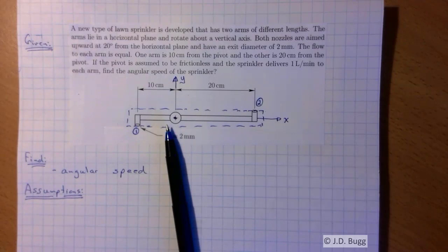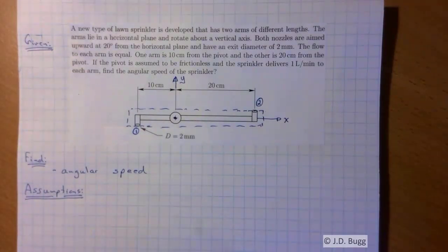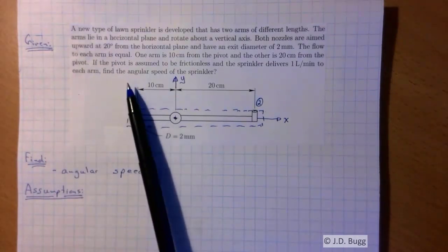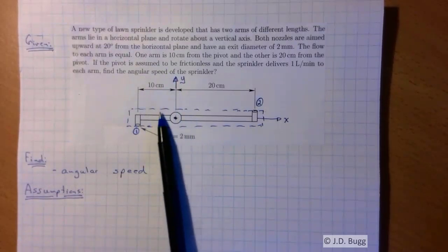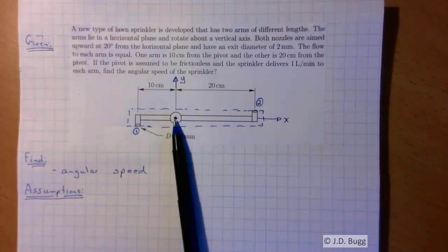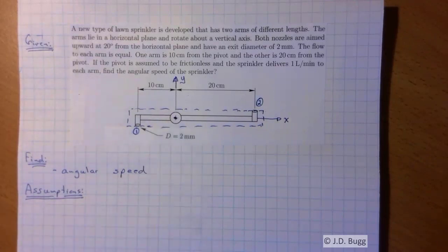So we can't quantify the torque due to the body forces, but we can say that whatever it is, it's going to be in the j-hat direction. Well, why is that important? Well, again, conservation of angular momentum is a vector equation, just like conservation of linear momentum was a vector equation. And if we think ahead a little bit, remember what we're asked for here is the angular speed of this sprinkler. Well, this sprinkler is rotating around the z-axis, so it's rotating in the k-hat direction.